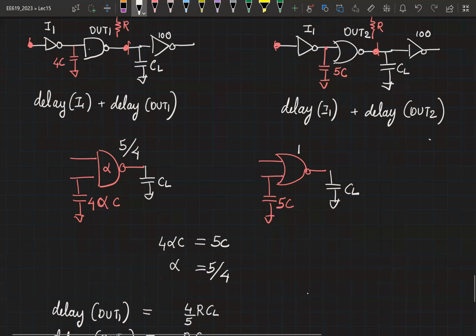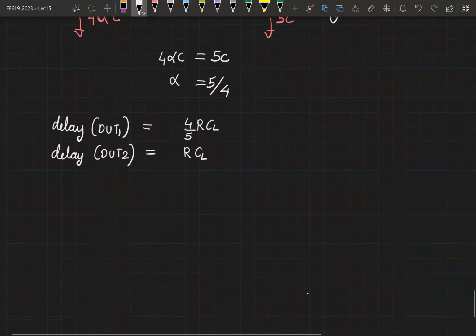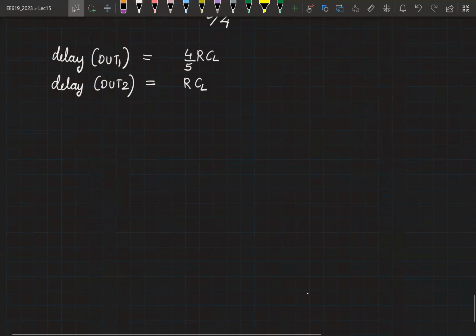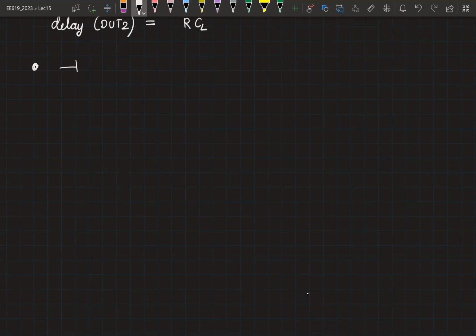So next step is, of course, to quickly calculate the logical effort for multiple gates. Let's say I have a unit inverter. What is the value of G? Yeah, so this will be equal to 1. So inverter is the only gate with logical effort of 1. Any other gate that you choose, any other logic that you're trying to implement with multiple inputs, will always have a higher logical effort.